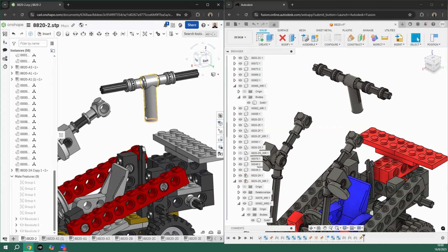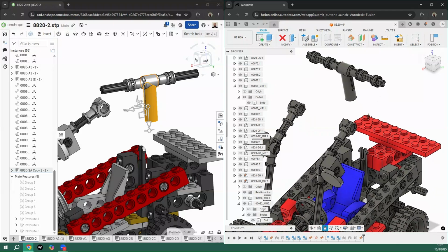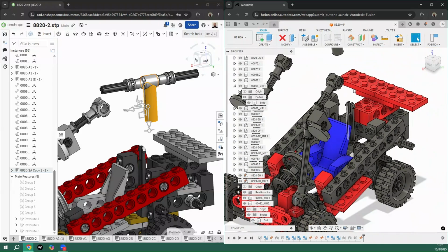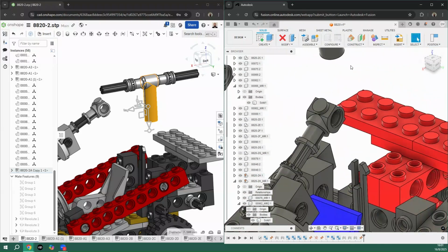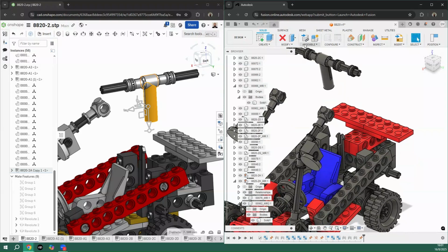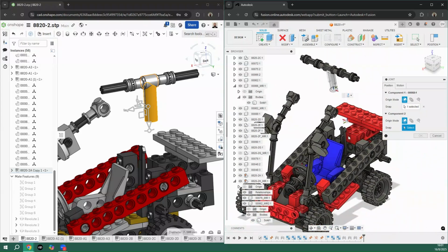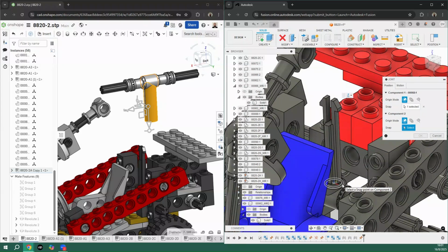Now let's get the section of the piston onto the slide condition in here. The question is how we're going to do it. On both softwares, there should be a way, but we will have to find out. This time we're going to start with Fusion. The most obvious thing I would say is to take a reference from the bottom to the bottom of the piston itself. So I will keep it simple. I will go in here, pick this edge, and pick this other end.